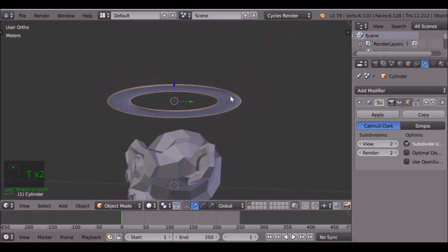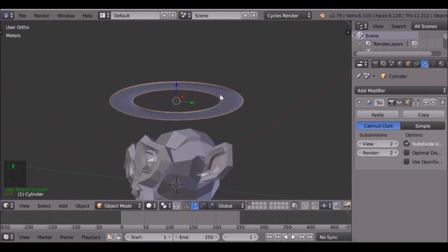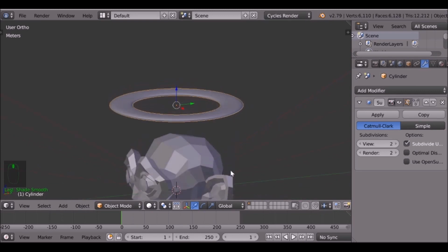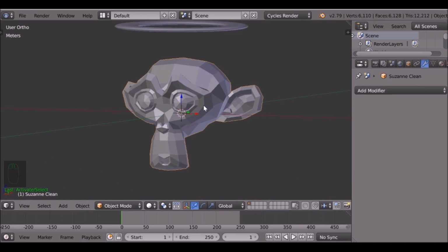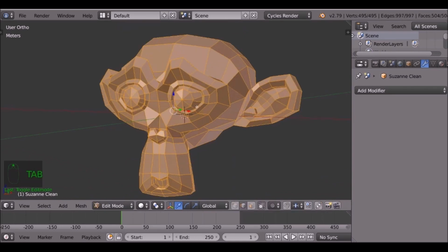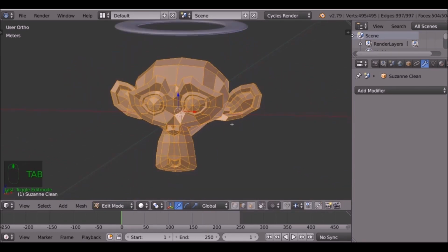That's a pretty simple halo shape. We're also going to add maybe a stand, and bring this down, and then sort of bend it. But let's go ahead and change some of the things on this head mesh first. So tab into edit mode. One thing to save us a little bit of time, we can actually delete half of this and then add a mirror modifier. So that's exactly what I'm going to do.